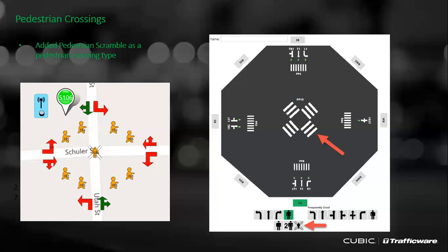Now, depending on your programming, I would probably have to see what kind of IO logic you have programmed and how it is connected for your particular use case, which may change the way the controller logs these alarms. But if phase 2 is extended, then there is an internal entry that the controller will make, and ATMS will see that. If the controller logs that for a different phase, in case you made certain modifications, then that is something we would have to take a look into.